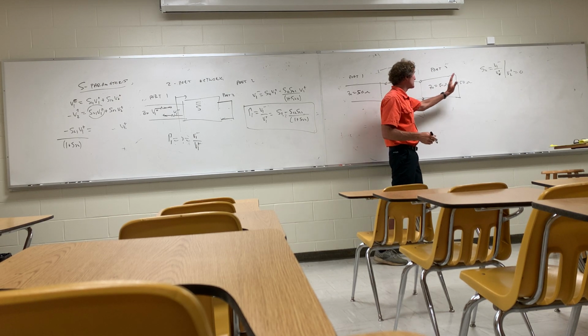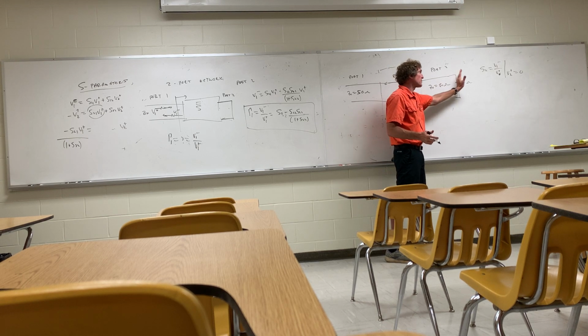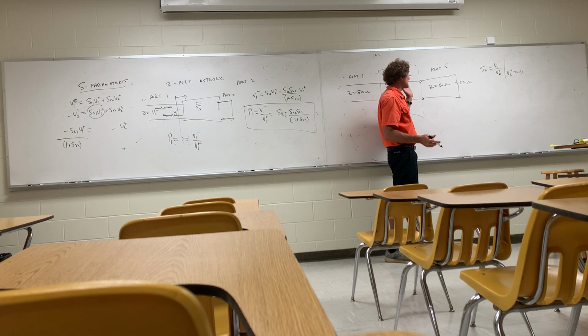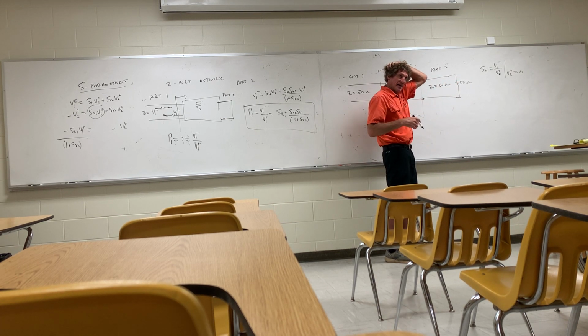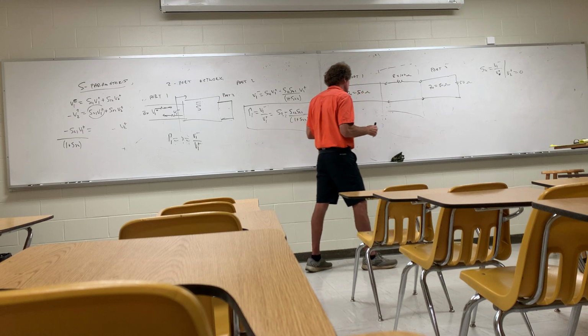If this wasn't 50 ohms, if it was 100 ohms, then there's a reflection coefficient here, and some of the signal that's transmitted through there would reflect back. So I have to make sure, at least mentally, that that is 0. It's called a matched condition.